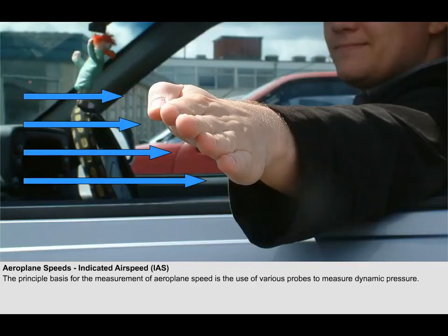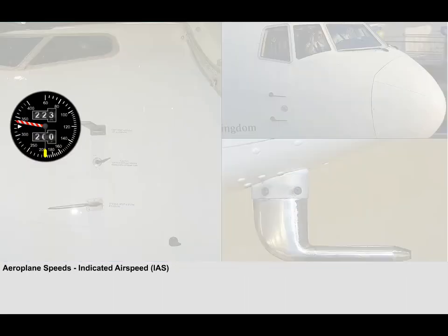You can feel total pressure by simply putting your arm out of the window of a moving car. However, total pressure probes, sometimes called pitot probes, and static probes suffer from errors. Without any correction to the errors, the speed which is obtained from the probes when dynamic pressure is being sensed is called the indicated airspeed, abbreviated to IAS. Indicated airspeed is the speed that is displayed on the airspeed indicator.